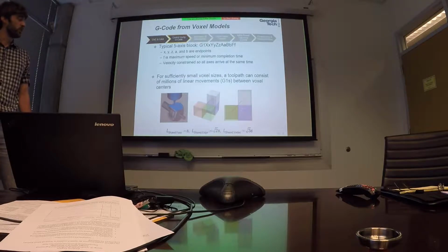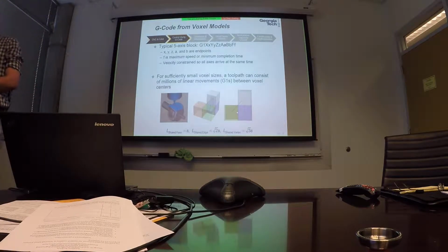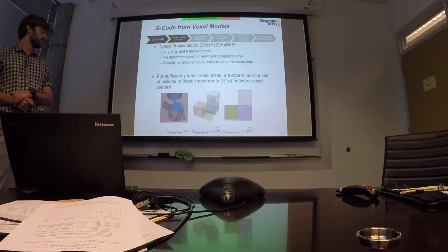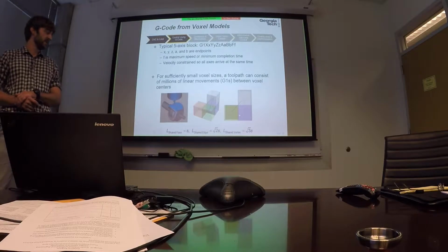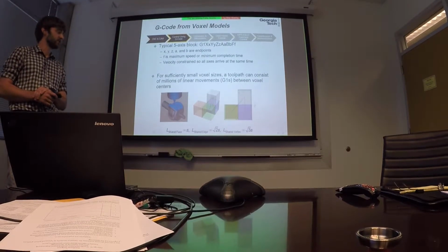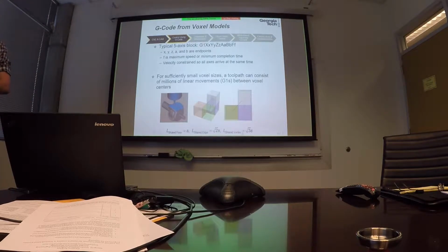Regardless of which move it is, typically, voxels for a machining operation will be on the order of tens of microns in size, and all of the movement increments here, whether it's shared face, edge, or vertex, will also be on the order of tens of microns. So the point is that the movements will be very small. Translational movements will be very small. Rotational movements will be determined by the resolution of the axis maps, which again is a user-selectable parameter.